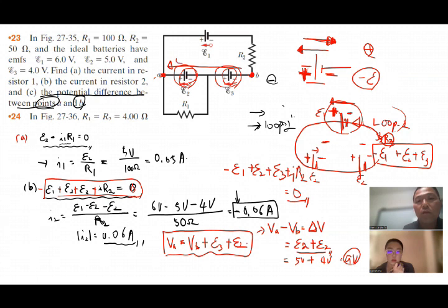But if you go along the opposite direction from the point A to the point B, the potential should drop by these 2 batteries based on that convention. Point B to the point A, because you are going along the same direction as the batteries, so 9-volt increase from point B to point A. So that is the potential variation by the two batteries, and the same as the potential difference between the two spots.